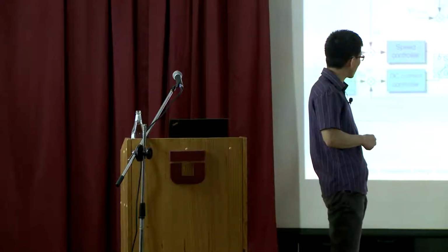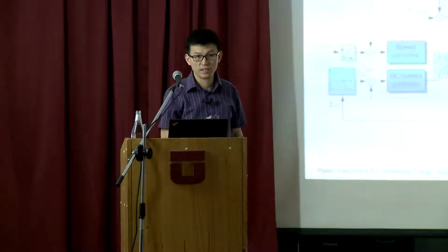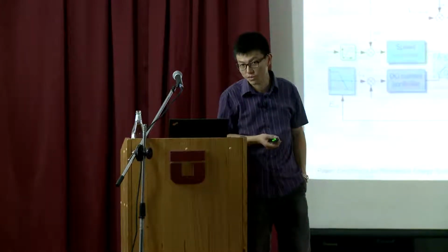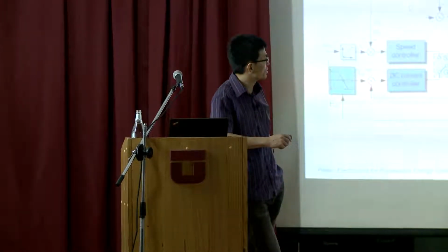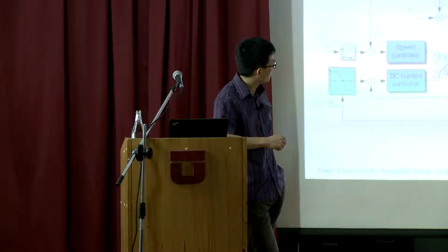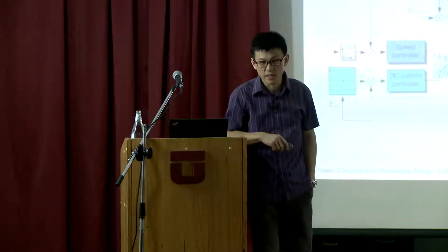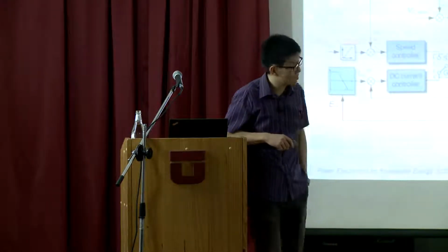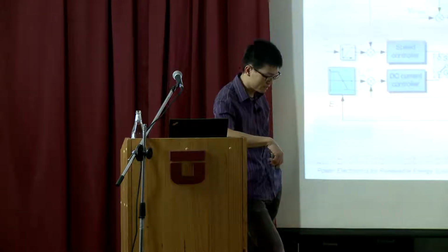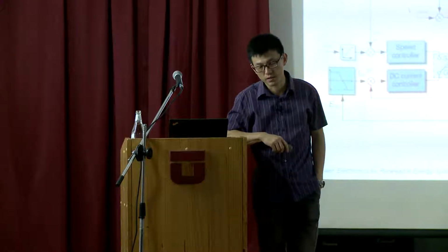One is called the ID current, which controls the flux, like IF in the DC motor. The other is called the IQ current, which is like the armature current. So for the control of the machine, you have a cascaded control loop. The current control loop, like in the DC machine, has the flux current, which is ID, and the torque current, which is IQ.